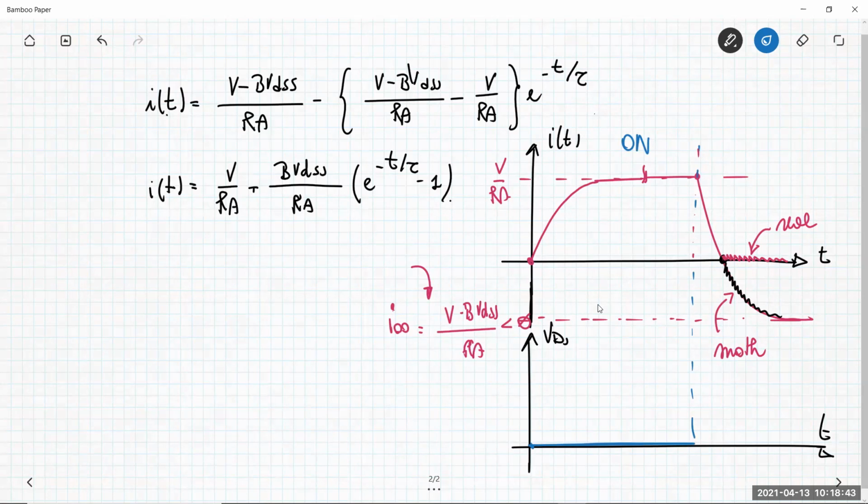We can say that it is R on multiplied by the current I(t), so it's the voltage V on. But basically, since R on, the resistance you have between the drain and the source in the conducting MOSFET, can be chosen to be very small, this quantity is very close to zero. So it's almost a closed switch. Then here it happens that the voltage goes very high.